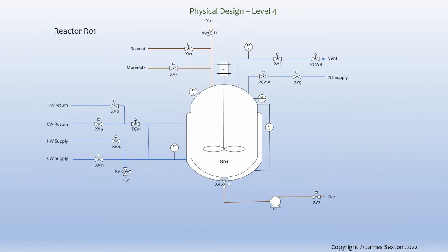For that, we need to zoom in from the process flow diagram into a P&ID type representation of the reactor R1 with a bit more detail for the reactor. Control modules are the lowest level in the physical model, the term control module being a collective name for all the instrument and controlled equipment normally shown on P&IDs.